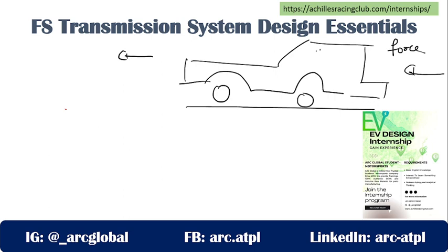Or if I say I've got a power source, my engine, this engine is not pushing, it is providing the rotation, right? Whenever anything is rotating, this force will be converted into torque. I will be talking about the torque now. So how much torque is required to be provided to my tire so that I would be able to take 100 kg of load?